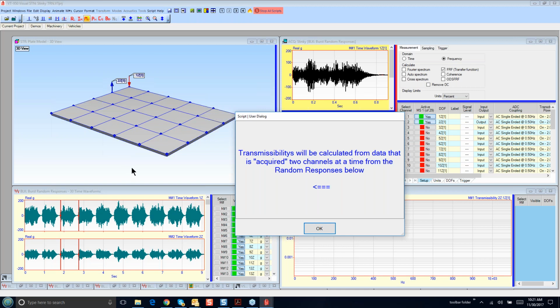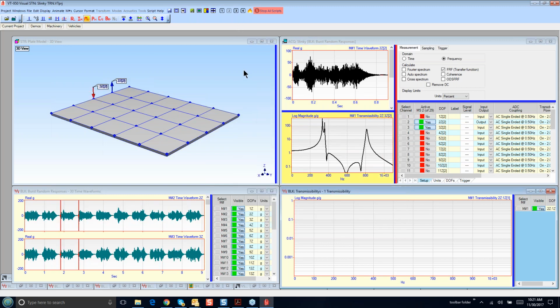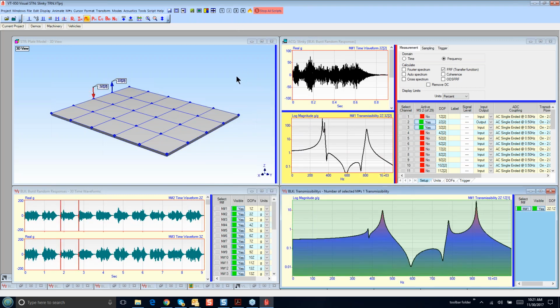Actually, we didn't curve fit the FRFs. We were looking at ODS. ODS is in animation, but the ODS is basically a contribution due to the resonances or the mode shapes. And on a lightly damped structure like this, you're going to see the ODS and the mode shape pretty much look the same. So let's go ahead and start taking the data.